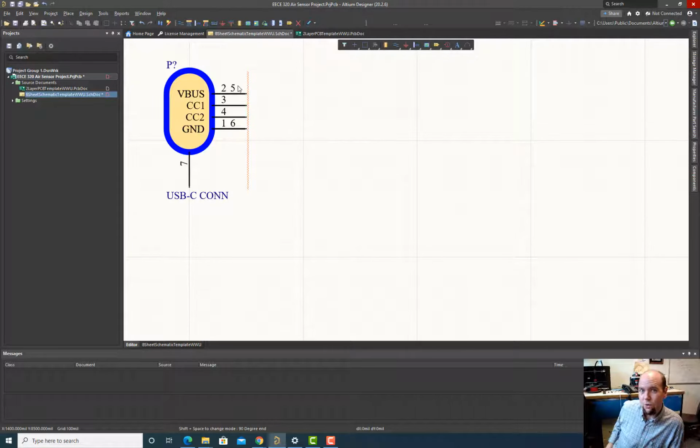Why might there be 2? Well, remember, this is a reversible connector. So if you want to have a reversible connector, anything you want to stay the same, even if you flip the cable, you have to have at least 2 of them. So that's what's going on here. There's 2 pins corresponding to the top and the bottom VBus and ground connections, which are on opposite sides. So if you flip it, it all stays the same. So 2 physical pins, 1 symbolic connection.